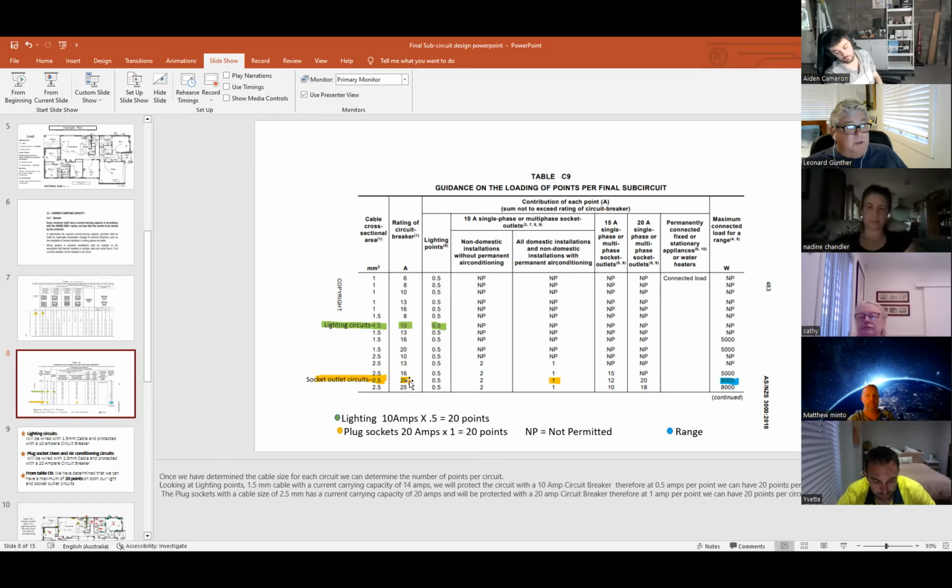ceramic cooktop. For induction cooktops, when we look at our permanently connected appliances like our stoves, air conditioning, etc., that's when we have to use Ohm's law and work out how many watts divided by the voltage to find how many amps that circuit's going to draw. But at this stage, it's only a standard oven, so we're allowed to run a 2.5 circuit for the oven there.